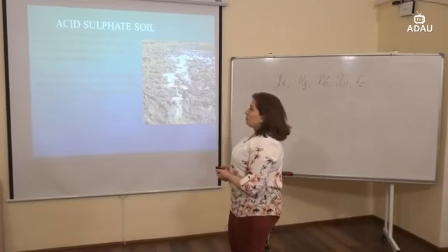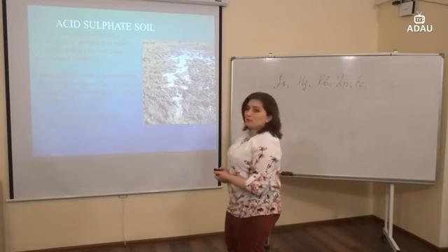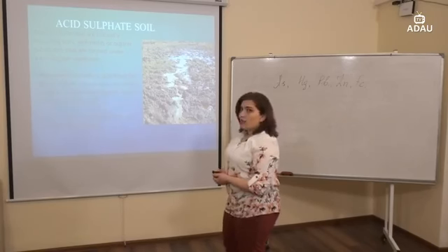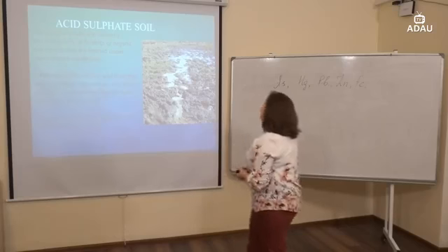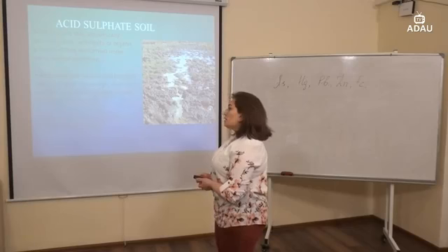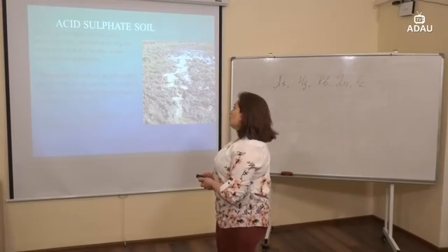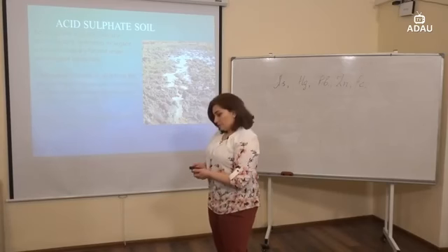Acid sulfate soil. Acid sulfate soils are naturally occurring soils, sediments, or organic substrates that are formed under waterlogged conditions. Release of this sulfuric acid from the soil can in turn release iron, aluminium, and other heavy metals, particularly arsenic, killing vegetation and other organisms living in the soil.